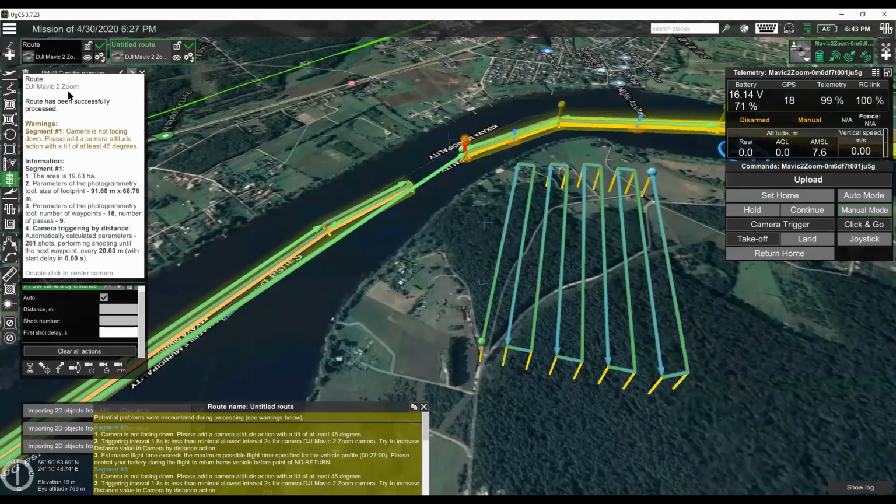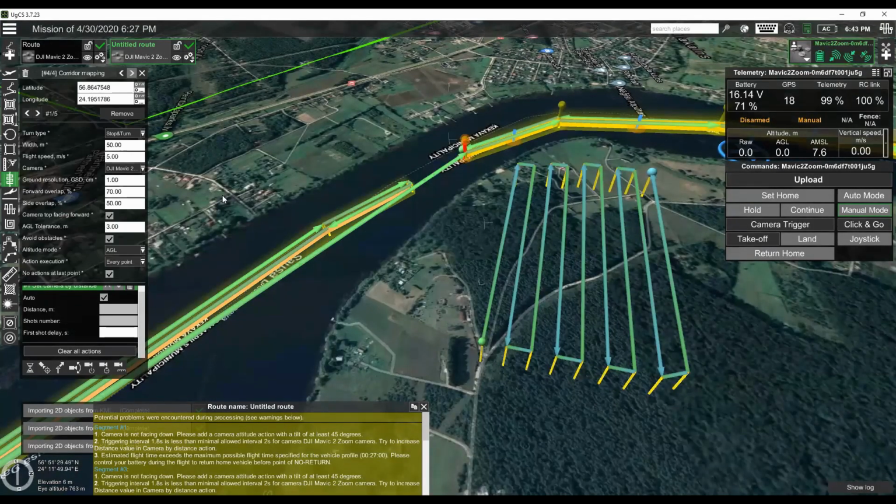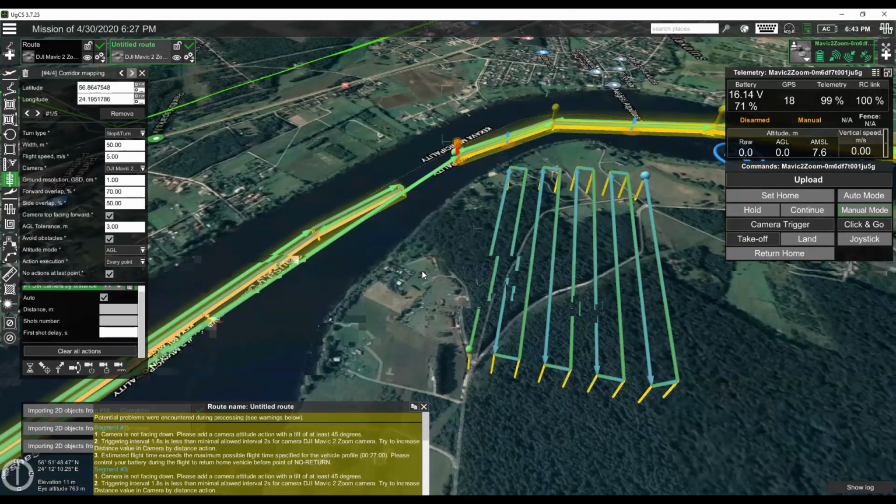So if you select in the drone profile an altitude of 2 or 3 kilometers, you will be able to create the route. But the limitation is at autopilot level, and a route with altitude above the one allowed in the autopilot, if uploaded, is simply not accepted by the autopilot. Now I'll check the Q&A section.